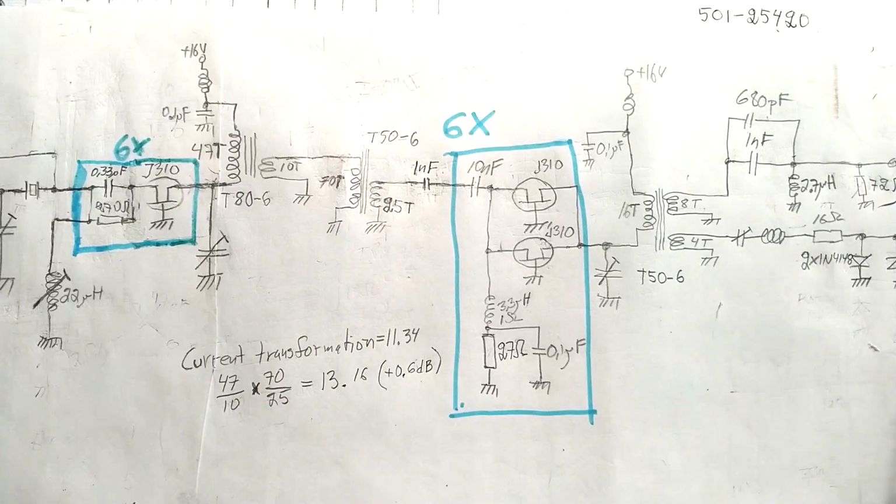I have also removed the 50 ohm load that was sitting here at the output of the feedback port. And that has given a significant increase in gain in the oscillator loop. I then adjusted the coupling capacitors to the crystals to reduce the gain somewhat, to have an output power of about 50 milliwatts.